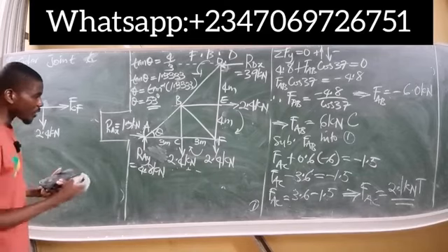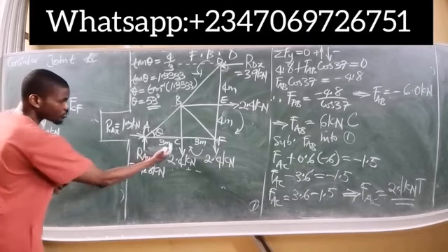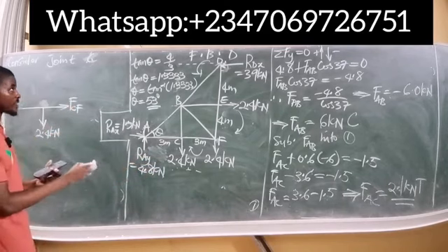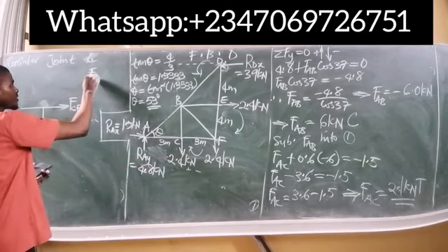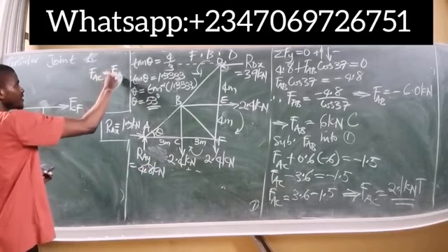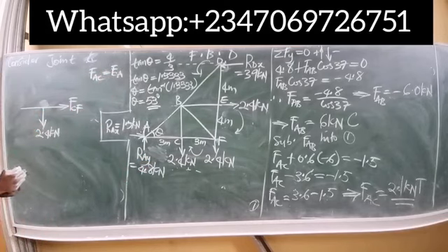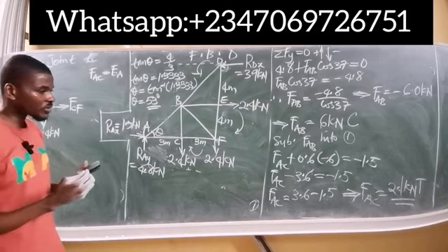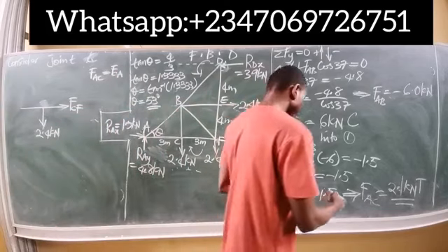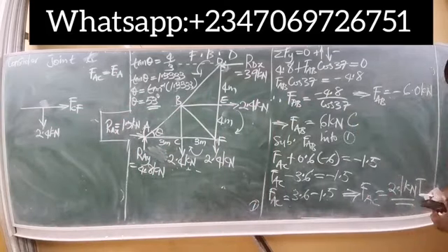Now, the first member between AC and CA is the same thing. I've always said FAC is equal to FCA. So these two forces are equal. Now, the direction is simply tension. FAC here, the value gave us 2.1 kilonewtons, and it says that the tension we assumed was correct. So the first member should be pulling out of the joint, not into the joint.